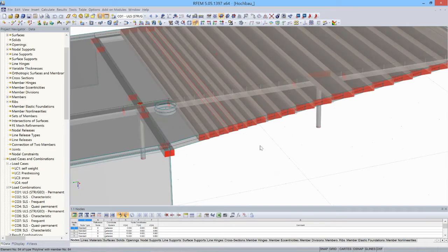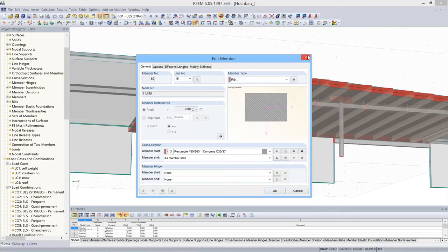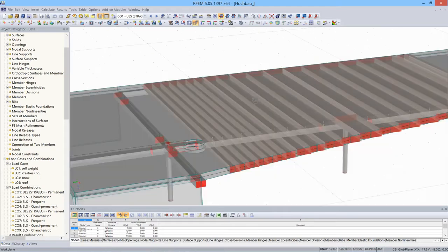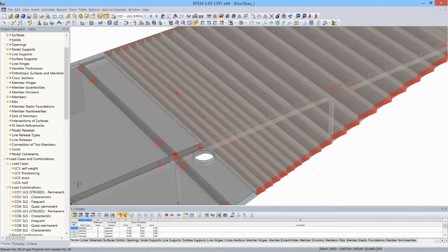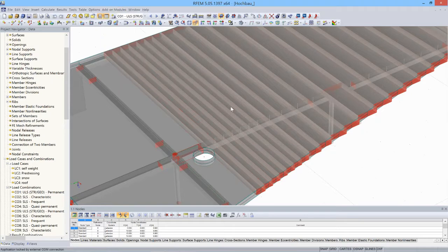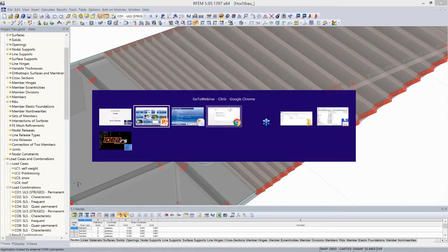You can see here that I have a rib which is linked to the slab, and RFEM can integrate internal forces from a defined width of the slab together with the rib, and we can get a T-section, which is then used in the analysis and in the design.